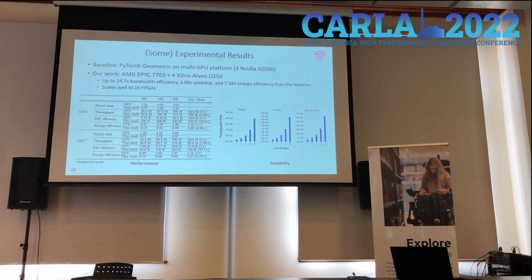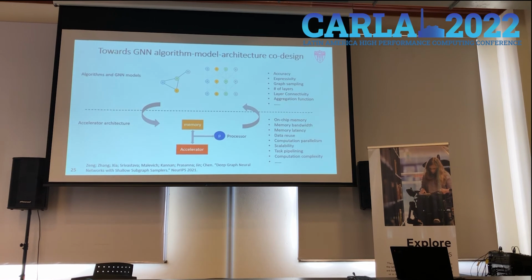So we performed these experiments using 4 devices. That's what we could have access to in my lab. And I'm showing here the scalability of these designs, using your performance model, looking at various data sets, and as we increase the number of FPGAs, what throughput improvement you can get in terms of scalability using multiple FPGA devices.